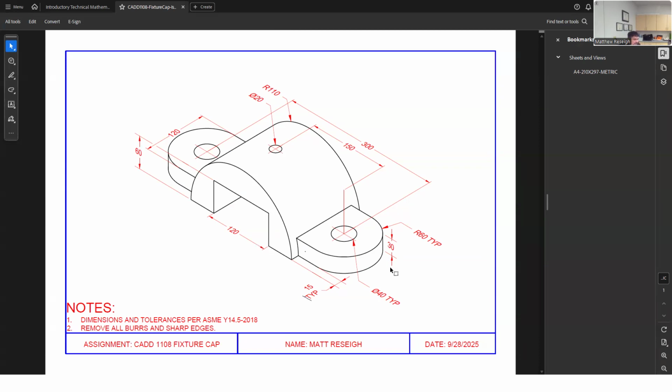And I would say a lot of times when I have a kind of round part, this is a half round part, a lot of round parts are two view parts. Sometimes they're front and right sides, and sometimes they're front and tops, depending. When you work with machinists, you do a lot of shaft details, like round shafts, which look like pipe or something. Those are usually shown in a front and a right side view. You get the round, but anyway, those are two view objects.